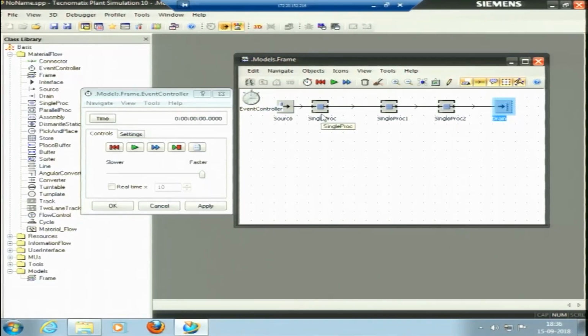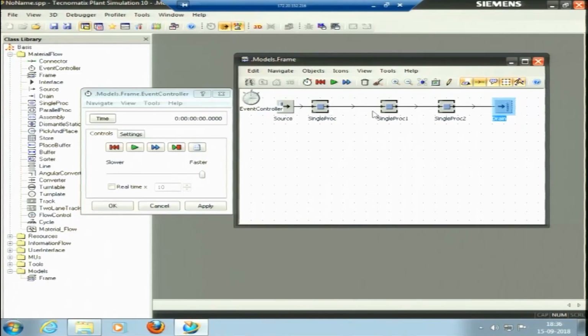This is ergonomics. If we talk about plant layout, this is work study, what is the minimum space that has to be kept. In manufacturing, the space between two machines, other than the width of the machine, is generally kept from 0.8 meter or even more than that, so that the workers can move in between. I have just kept it at a random location here.